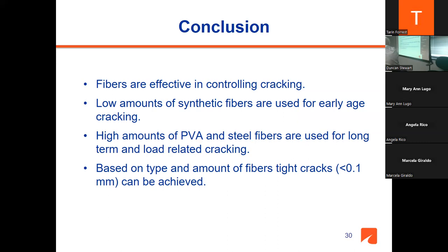Very effective. As you see, if we have the right concrete, we can keep those cracks very tight. There will be cracks, but very tight cracks, difficult to penetrate into. And based on type and amount of fiber, tight crack can be easy. So this is the presentation. And thank you for the opportunity.